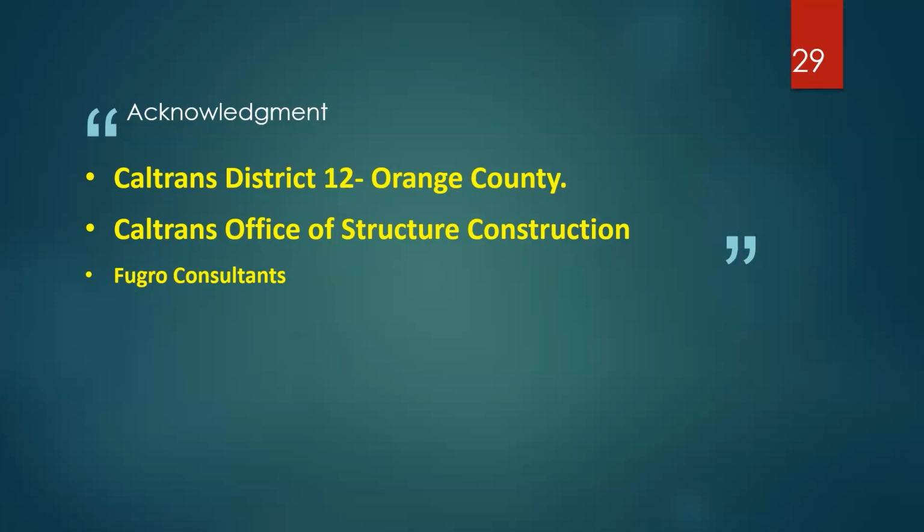That's another great question. And that's exactly what we did. Because of the mandate for not using batter piles in liquefiable soil, we had to make sure that we have a great and robust site characterization to capture those elements. Otherwise, some could have argued we use the borings and we don't capture those layers, there is no liquefaction, and we would have ended up using batter piles. So in that aspect, it helped.